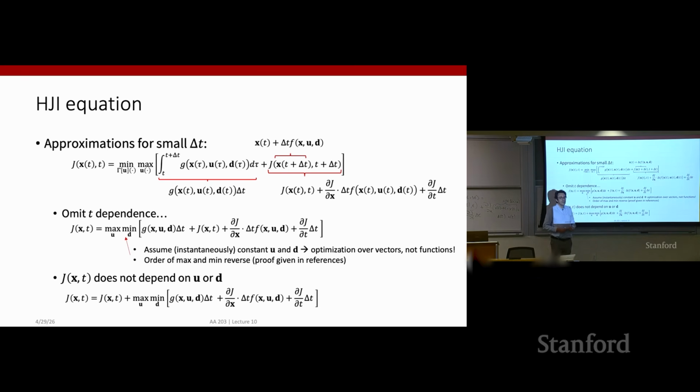Yep. Sorry, so why couldn't we write max-min since the beginning? Because here, this min-max and this max-min have a bit different interpretation. Here, we're doing nested optimization over the space of controlled sequences. Here, we're doing nested optimization over the space of instantaneous control. So within this terminology, it turns out that to give the disturbance an advantage, it has to be part of the outer optimization. That can be understood, but it would require a deeper discussion to be super rigorous. So that's what I'm saying.